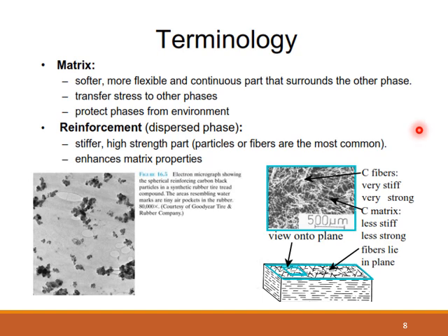Those things you see on the modern day car that you think are plastics or polymer, it's not a pure plastic or a single polymer. It's some designed polymer that is reinforced, either reinforced plastics or some reinforced polymeric material. Most of the essence is that if you build the dashboard of a car with a polymer, the result you get is different from when you build with a metal. A metal makes the car heavy. If the car is heavy, it will increase fuel consumption. It will also lower the speed of the car. But if you desire a lightweight material and you want to retain certain mechanical properties, then the best way to go is to look at the design of composite material.